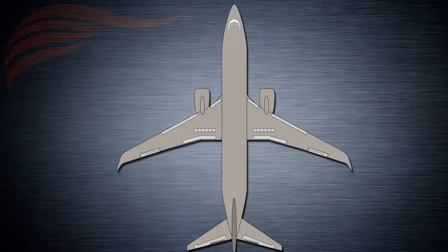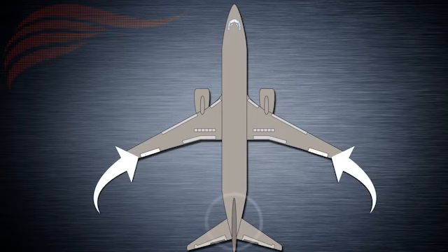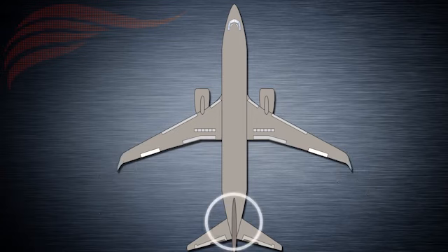Dutch roll is an aircraft movement where the tail moves from side to side when there is input in the ailerons or rudder. In smaller aircraft, this condition is partially dampened. However, in larger aircraft, auxiliary systems like the yaw damper on the 737 NGX are used. This is due to the faster airspeed and higher altitude at which they fly.